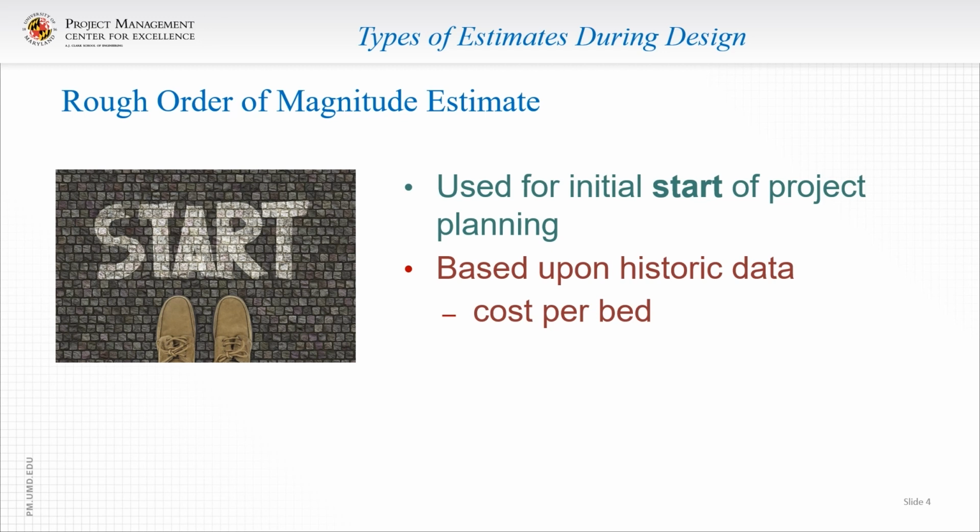If the costs are developed according to a national average, they must be adjusted using the appropriate city cost index. Costs taken from past projects must be adjusted to current or future dollars. If the project is similar or larger than normal, the cost is adjusted for size. An appropriate contingency should also be applied to allow for scope adjustments and economic or market conditions.